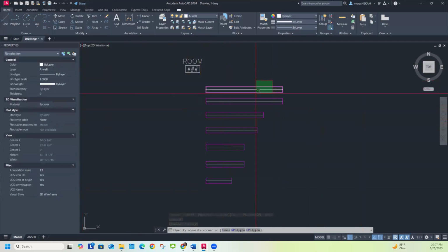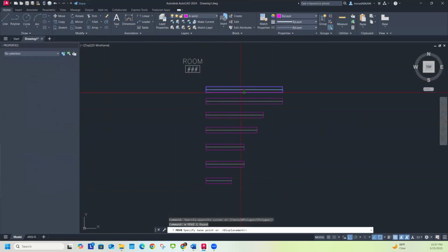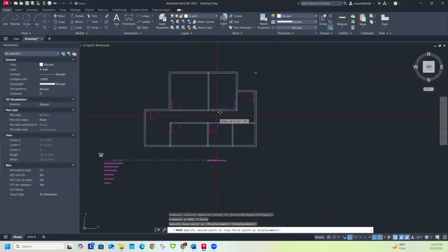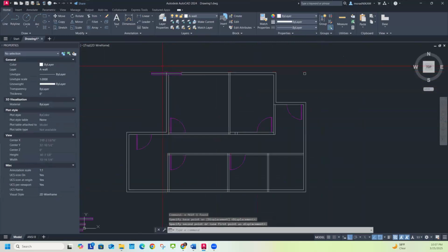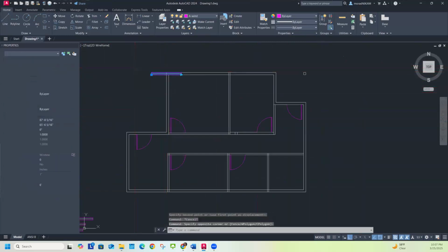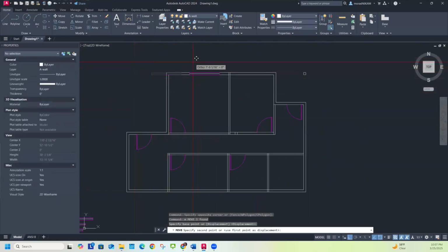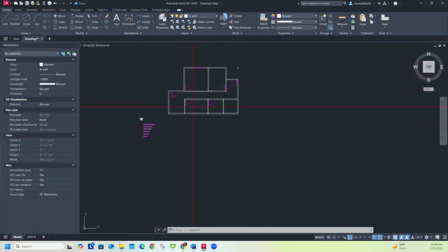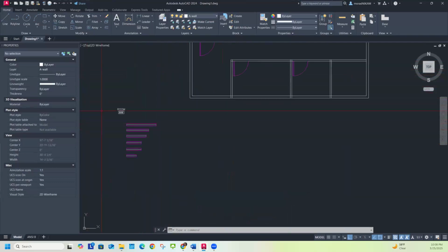And so these are measured from the midpoint to the exterior wall. So I'm going to move this, and I'm going to select this midpoint and put it right here. And so now I need to move this one over 8 feet 6 inches. No, that doesn't look quite right. Oh no, actually it does. Yeah, because it's not going to be in the middle. Okay. And then, while I'm doing the dimensioning, that'll kind of tell me if I did anything wrong.